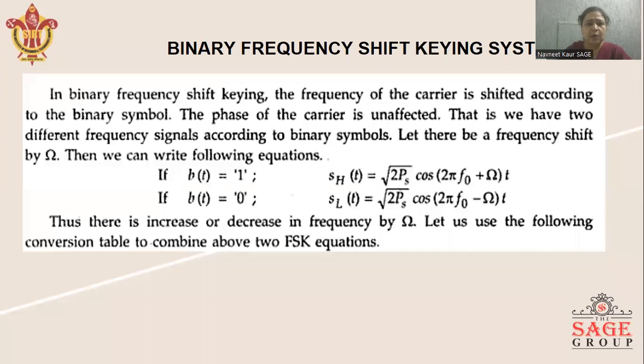Now first, what is BFSK or Binary Frequency Shift Keying System? In the BFSK system, the frequency of the carrier signal is shifted according to the binary message symbol. The phase and amplitude of the carrier will be unaffected.